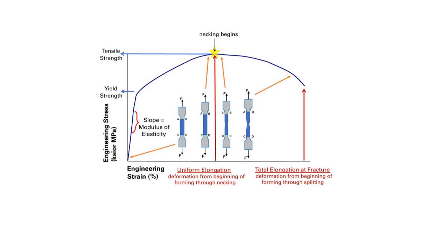After the load application, the load is reversed and the specimen is removed from the apparatus. Using relations like Young's modulus, yield strength, and ultimate strength, we have to determine the material characteristics. Some of the factors affecting the tensile testing are specimen preparation and specimen size, rate of straining, temperature, hydrostatic pressure effect, and radiation effect. Apart from this test, we have various forms of tensile test like tensile adhesion, tensile shear, tensile grab, tensile pulling, tensile fatigue, and tensile creep.